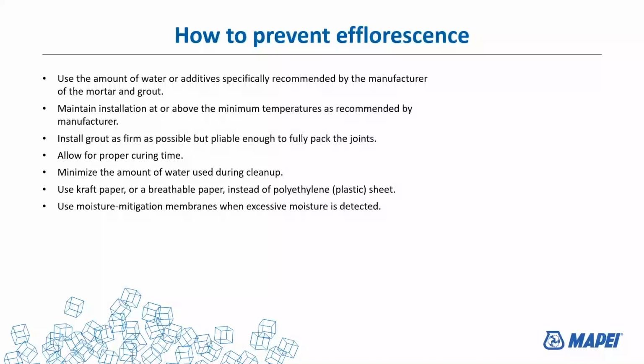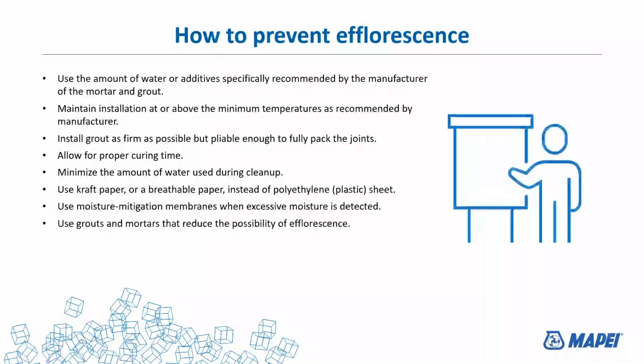In today's technology, there are a variety of grouts and mortars that can be used to reduce the possibility of efflorescence. Some of the new calcium aluminate type grouts are considered efflorescence-free grouts. Our UltraColor Plus FA would be a perfect example of that. Another example would be the Flex Color CQ being moisture-free, no water added. And, of course, epoxy grouts, 0 water. So those types of grouts help reduce it. Standard cement-based, Portland cement-based grouts always have a tendency to, or have the ability, I should say, to effloresce under the conditions that we've been talking about.